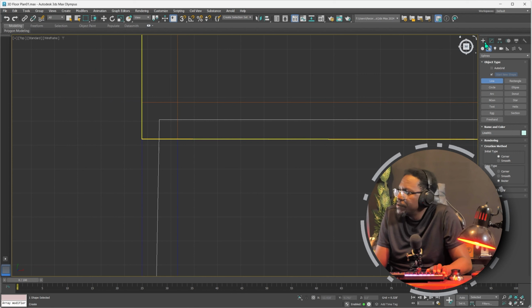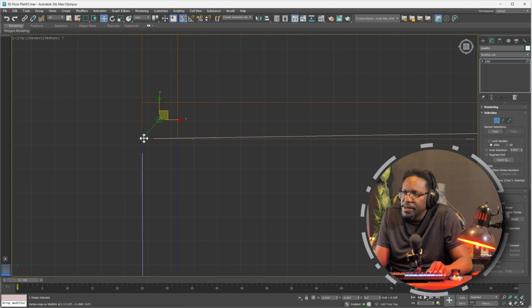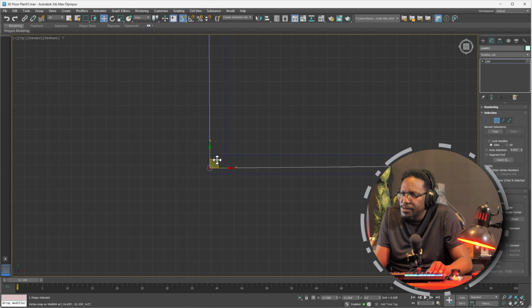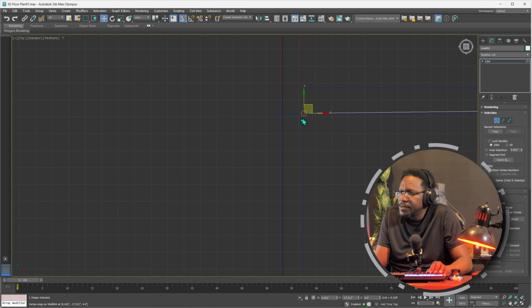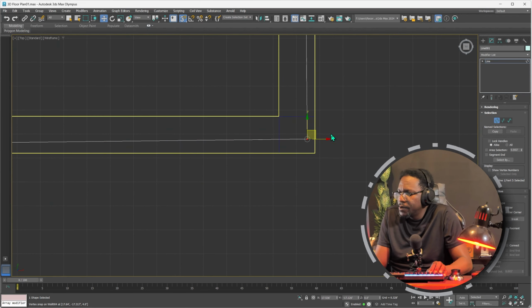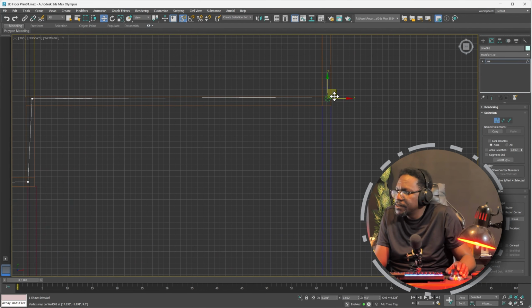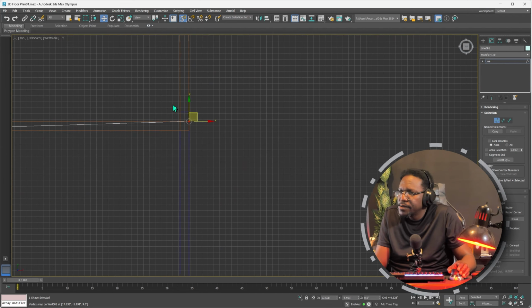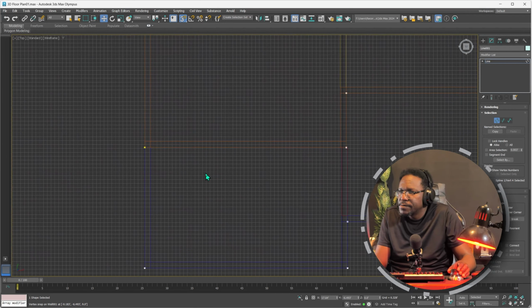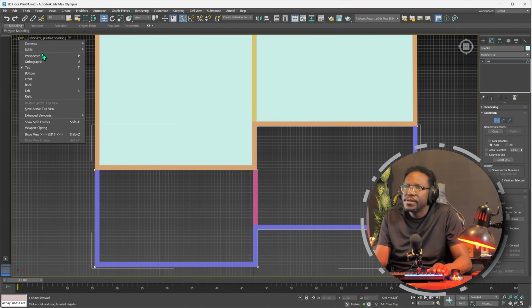All right, now I'm going to go to modify and select these edges here. And now I turn on snaps so that I can snap them to these edges. This is an approach I use when doing snaps, especially in 3ds Max. I'd rather draw the lines rough, and then use the snap tool. Let's snap this here, maybe snap this one here, there, and snap this one here. All right, great. So now go to shaded and perspective.